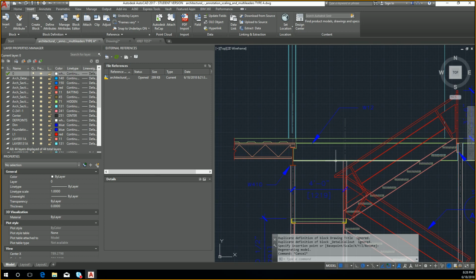When you have the offset shield, right, doesn't have the inside structure. Yeah, it's whatever you can scan. So there's ways to do internal scans too. Depending on the cost of your scanner is depending on how well it can scan. So there's systems out there that are very simple. They're about the $10,000 range, where you would actually place it on a tripod, and you would aim it at certain points after calibrating it, and it would know the distance X, Y, and Z away from your station. So that's what you would create with a point cloud.